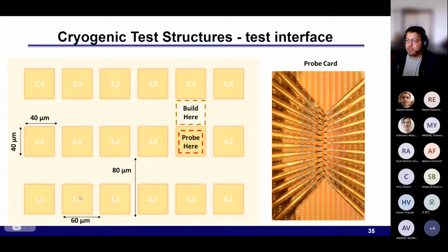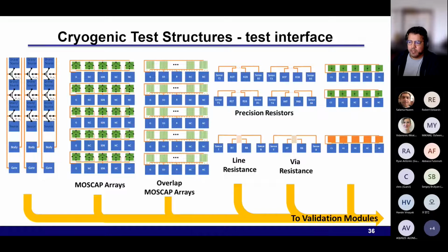One of the constraints of these test structures is that the probes need to have around 40 micron distance. So the structures are small, but they need to be squeezed in there. The reason is because of the probe card, like in the picture on the right. So using OpenFASoC, we started using GDS Factory so that we could do more customized design. And that was an enabler for OpenFASoC because we started doing things that we didn't do before. The reason goes back to the enabler, which is automation in open source.